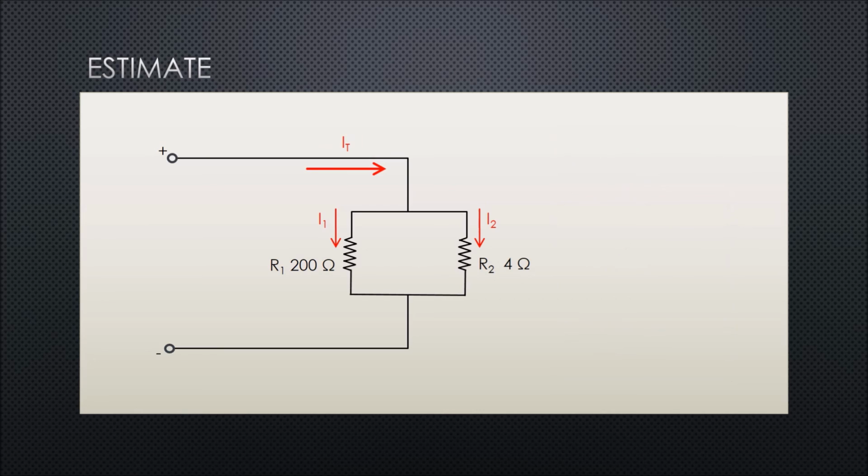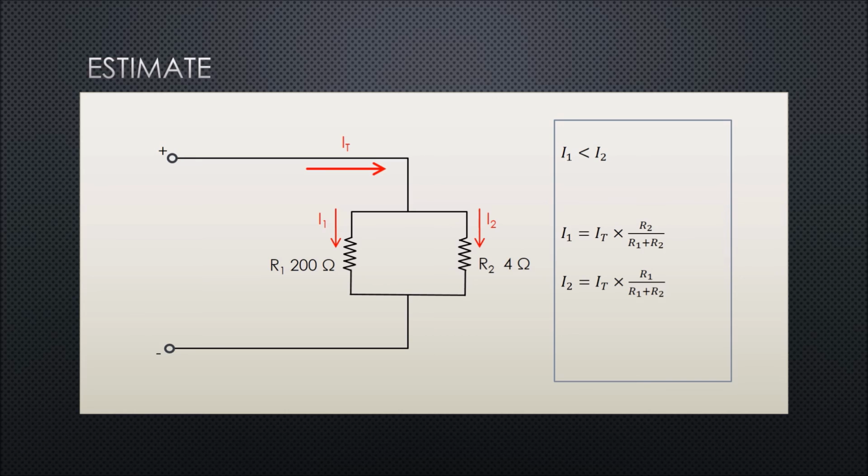By considering the water analogy, you are able to estimate a value in your head before attempting a problem by knowing that there should be less current through the larger resistor. Therefore, if you get an answer that does not go with your estimate, you can go back and see where you went wrong, often using the wrong resistor value in the numerator.